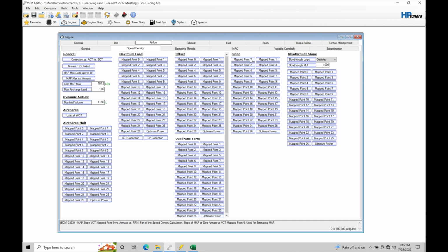But the problem is going to be if we get into a transient type of condition where we have a large throttle change and a large burst of airflow entering our engine. The mass airflow sensor can't sample fast enough and doesn't give the engine control module the proper air mass registration in that transient type of condition. And that's where we fall back on this speed density airflow estimation. It's not a measurement, it's not going to be a registration of airflow, it's going to be an estimation.